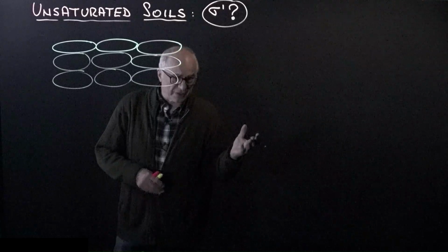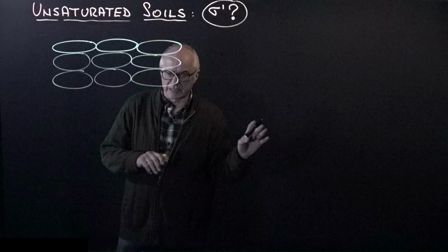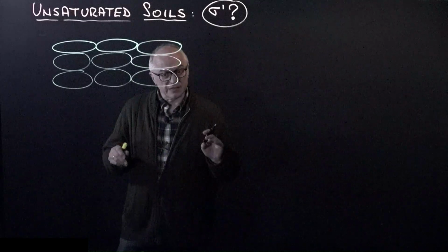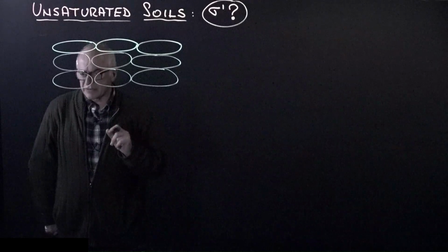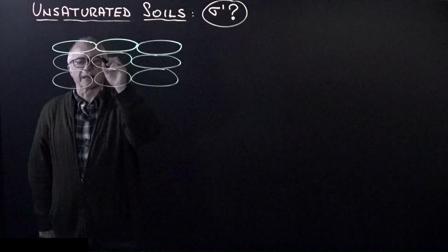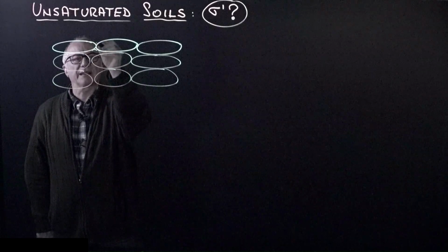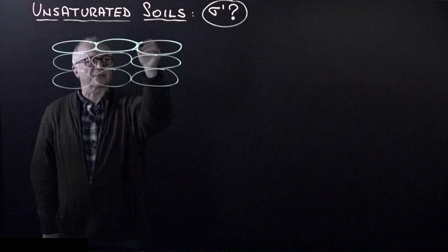The previous example addressed the issue of spatial variability, heterogeneity. Now, what about the case of anisotropy? It is also tricky. Let's say that we have reached the pendular regime, whereby water remains only at menisci, and we create menisci, all of them of the same curvature, at contacts between particles.